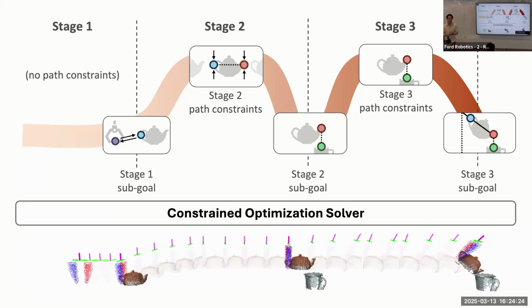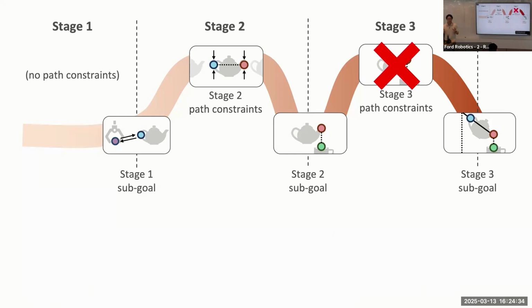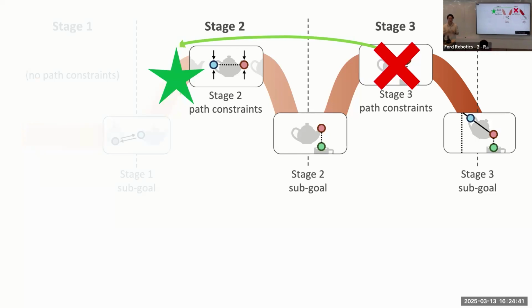Then you can do constraint optimization to optimize the robot's actions. This is essentially sequential quadratic programming to optimize the robot's actions. One interesting thing about this framework is that whenever a constraint is violated somewhere during this process, you can trace back to some earlier part of the whole task-level plan, until a point where all the constraints are satisfied.